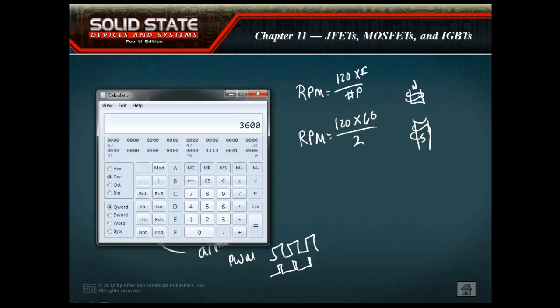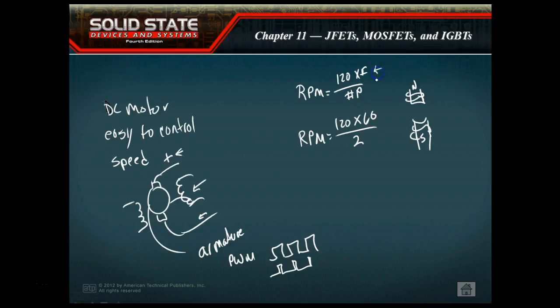So normally we've got two ways we can control the speed of a motor. We can change the frequency applied to it, or we can change the number of poles. So a 4-pole motor will run at 1,800 RPM. If you've got a ceiling fan in your house, this is exactly what you're going to do. If you ever took the switch apart, it's got 3 leads on it. When you go from low to medium to high, you're selecting a different number of poles, which causes the motor to run at different speeds.